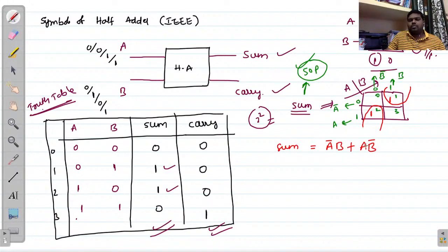So we can write this directly also because of two variables. How can you write? This A should be considered as 0. Just focus on active combinations only. In the sum column, we have these two active combinations only, so for these two you can focus. This A having 0 and B 1. In sum of product, A equals 0 means A should be considered as the complementary variable, A bar. And in the sum of product, B equals 1 means B should be considered as uncomplemented variable, right?